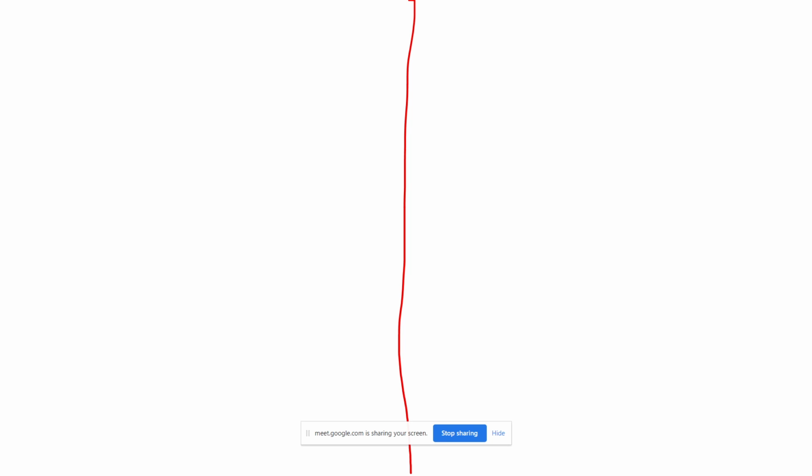Now another question, another derivation which is important to you: what will be the optimum pressure ratio for the maximum work output? Because ultimately we want the work output to be higher, so that efficiency can be higher.